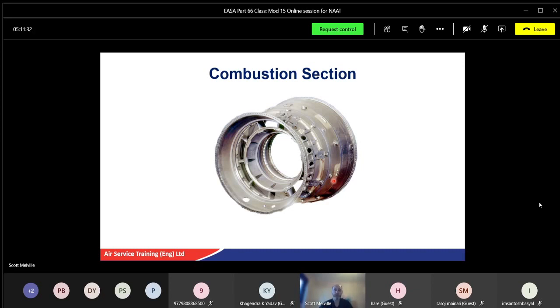It might be heat shields surround them, and where the fuel burners go into the casing, this should be checked for security, damage, etc. Ignition cables, routing, the little vibration clips. Again, check for burning potentially. Drain pipes, again, check they're not blocked, for combustion chamber holes, potential fire hazard. Some aircraft have drains collected in a tank. The tank may require to be manually drained. Some will actually drain back in the engine, but some of them just need to be drained initially as well.